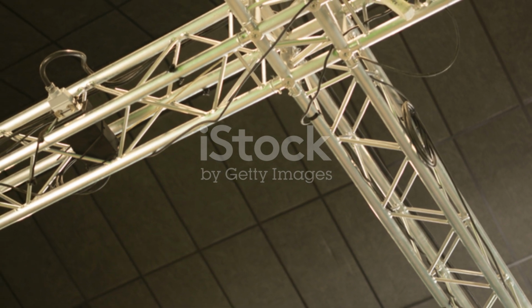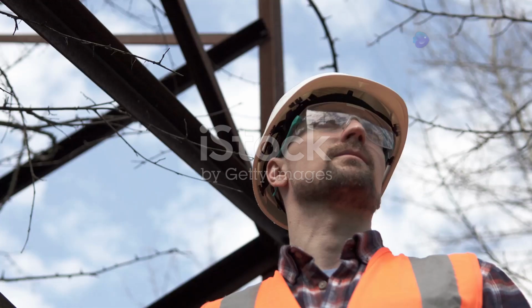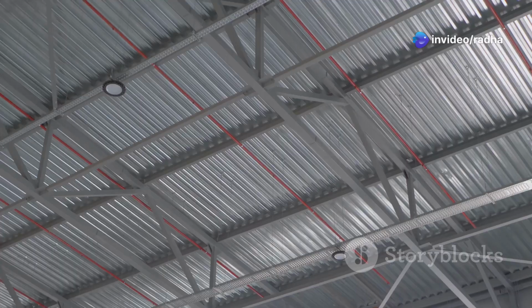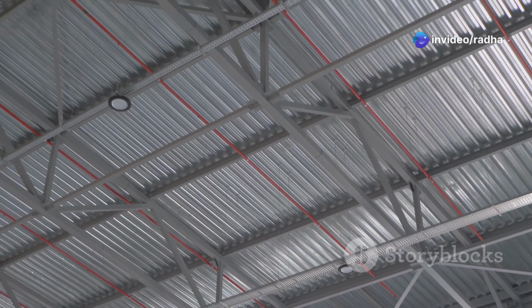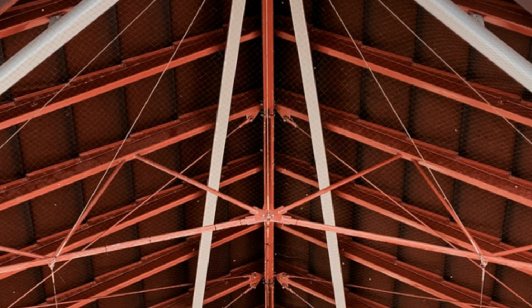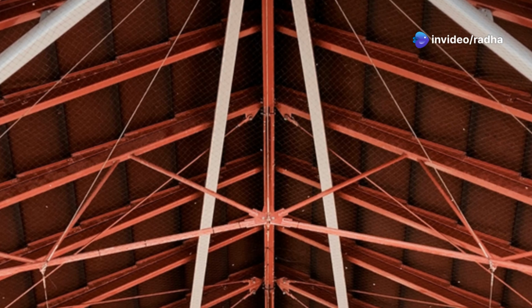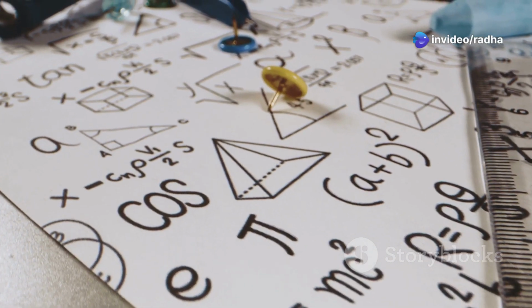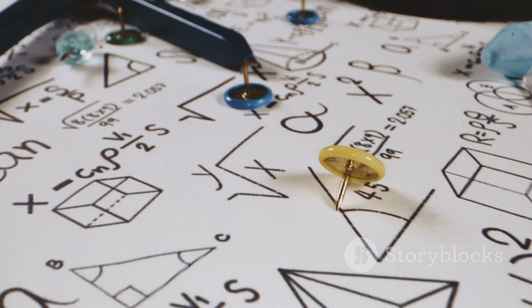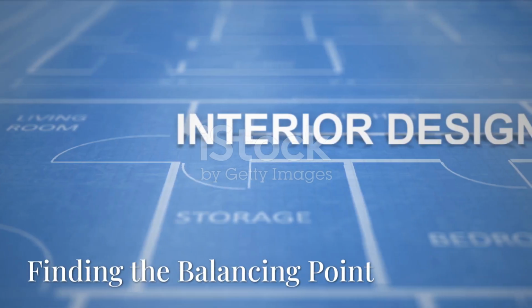Section 5. Analyzing trusses, method of sections. Another powerful tool in a structural engineer's arsenal is the method of sections. This method is particularly useful for analyzing larger and more complex trusses. Instead of analyzing individual joints, the method of sections involves cutting through the truss and analyzing the forces acting on the resulting free body. By applying equilibrium equations to the free body, engineers can determine the internal forces in specific members of the truss.